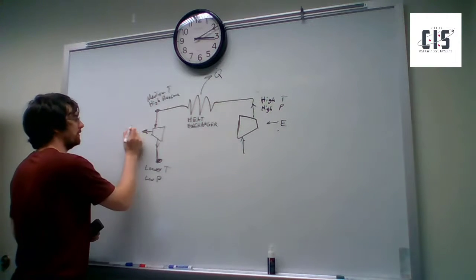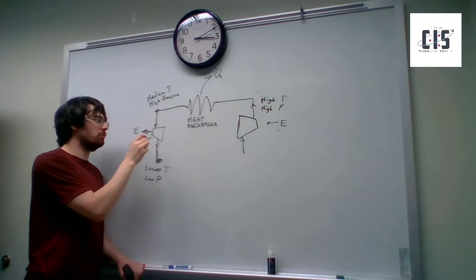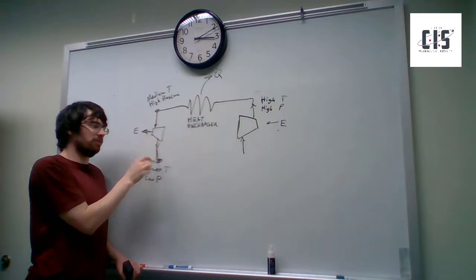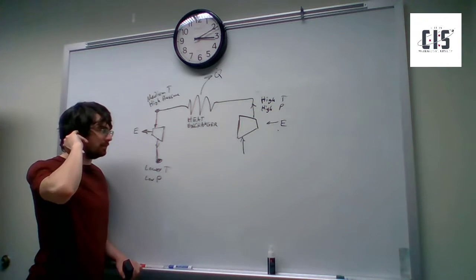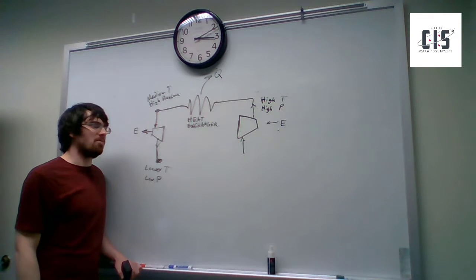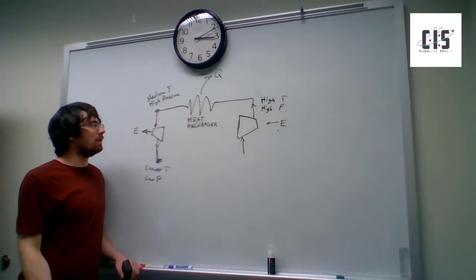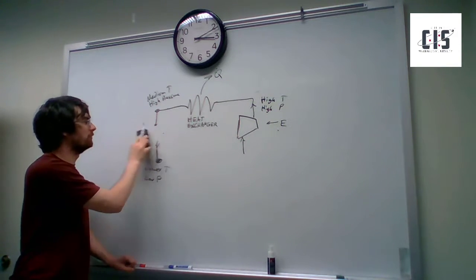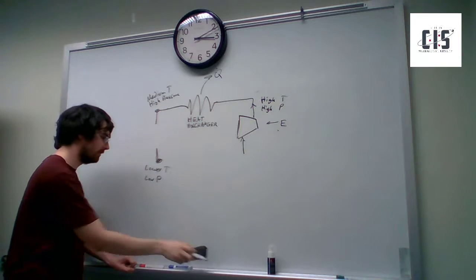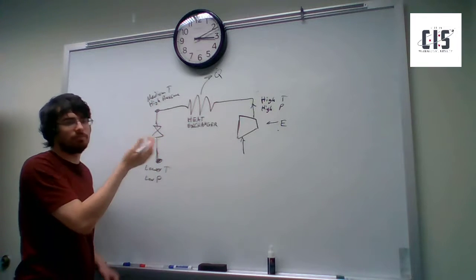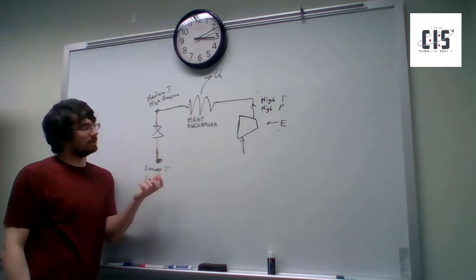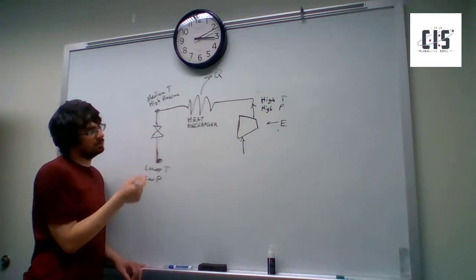But the thing here is you now have a moving part in the cold side. It's going to get very cold inside this turbine. And the difficulty is that makes it a lot more likely to break. Okay. And so for that reason, household refrigerators don't have turbines. They just use the throttle valve. Super cheap, pretty much never breaks, no moving parts, yada yada. So it's not as efficient, but it's useful.